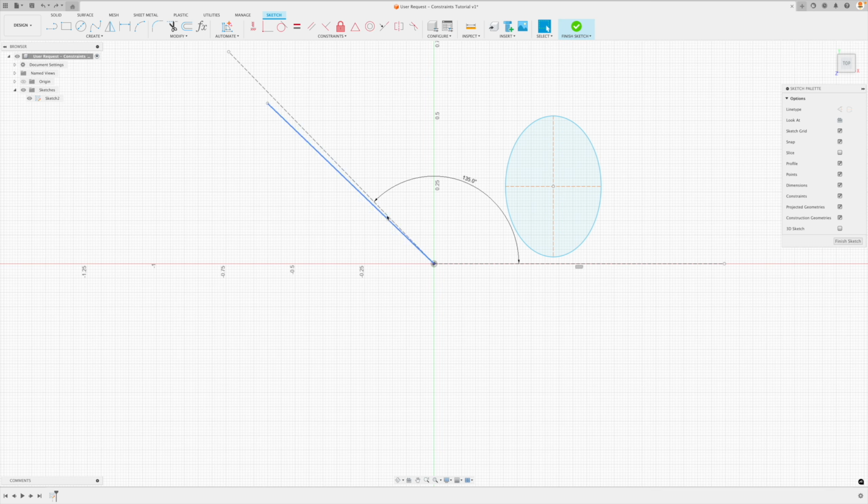Well, why? Because we've got this 45 degree line right here. Usually we have an imaginary 45 degree. So this is saying if this line is below 45 degrees, it's going to default to our horizontal axis. If our line is above the 45 degree mark, it will snap to the vertical axis. So this is constraining this particular line. I am going to delete that and our imaginary line over here. And you can see it actually created an additional construction line to constrain the line that we just created, to put an angle on it.